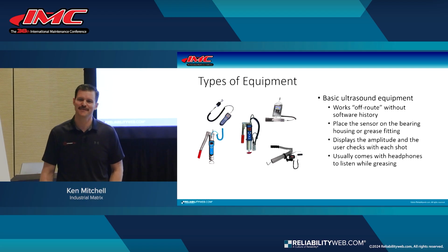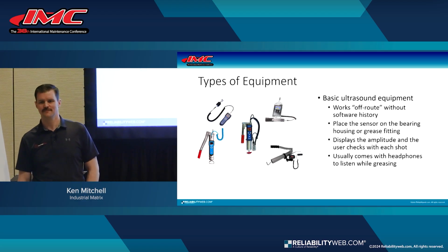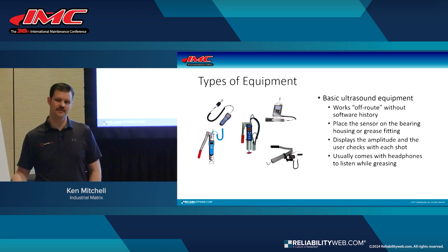When you're talking about auto lubers, were you talking about the smart lubers, where the sensor activates the smart luber when it goes below a certain decibel level? Exactly. Typically above a certain decibel level. In the continuous type of systems that are becoming more predominant, you're monitoring that bearing, sampling every minute, every 5, every 10 minutes, depending on the parameters.